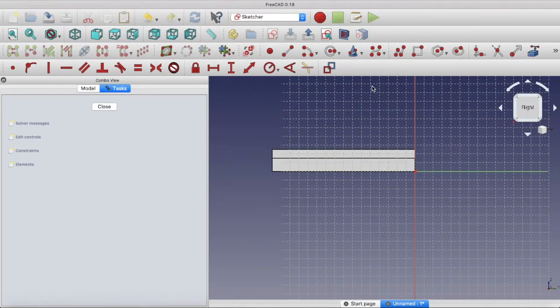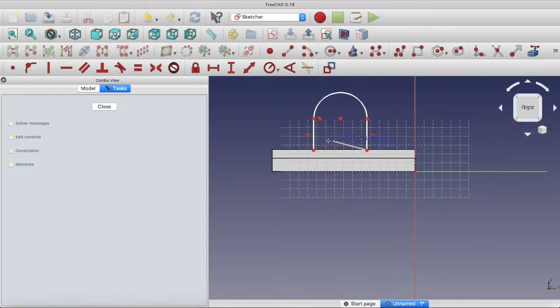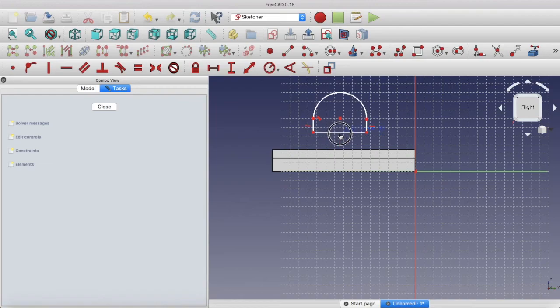For creating the sketch, we select the polyline tool again and start drawing the profile. Just keep pressing M key repeatedly till you get onto the tool and draw the arc, and then again change over for drawing a free line and come back to the start point and finish the sketch. This is a free sketch.